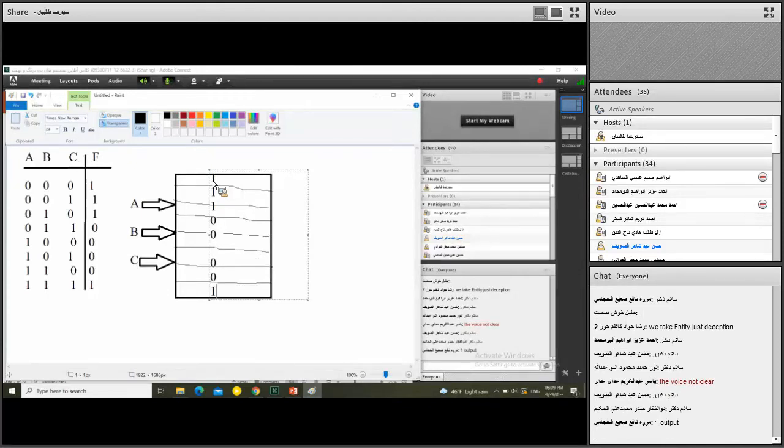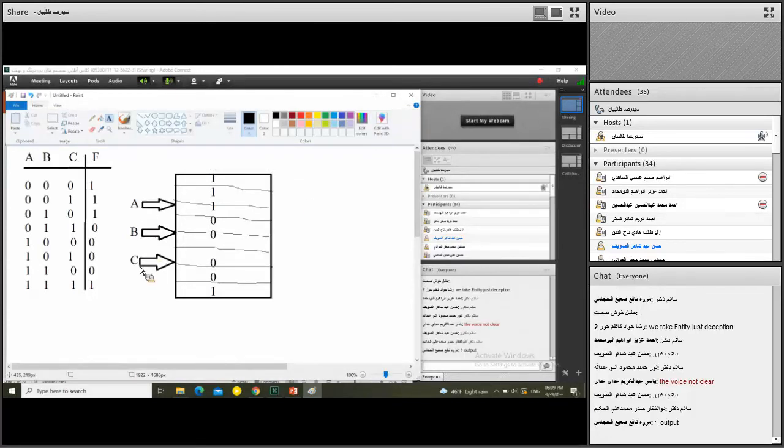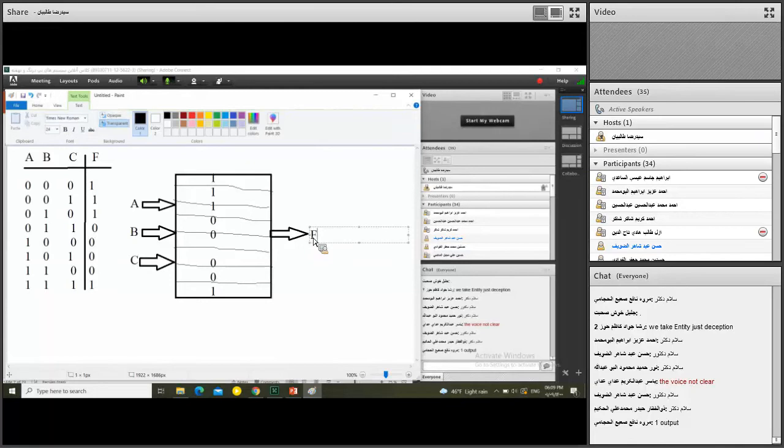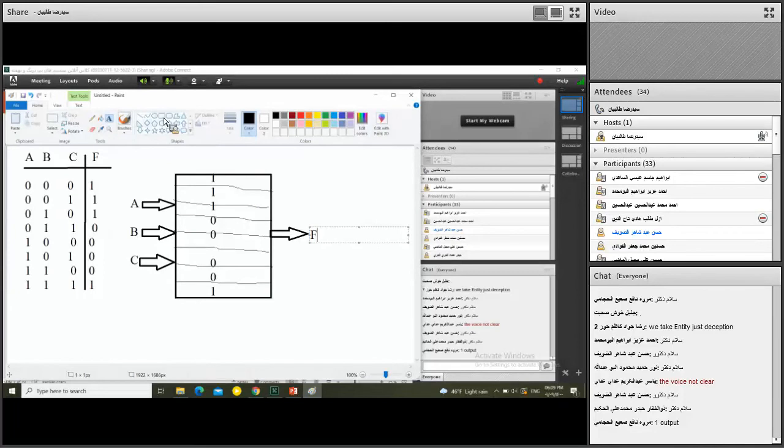Now we can see that in different conditions of the inputs, we have the value of the logic function, and really we have one output, and this output is the logic function F. By this simple consideration, we can implement this logic function F. By implementing a memory with these few inputs and few cells, we can implement every logic function.